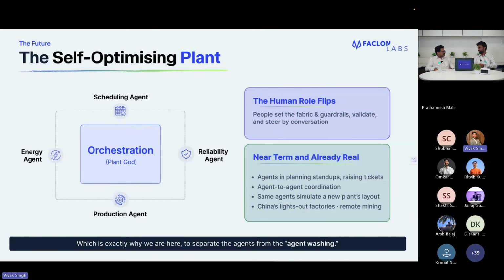Definitely. Maybe at some point in time, the quality agent flags that your main CTQ parameter is now deviating way out of normal. Then there might be a process control agent. The quality agent would flag that your CTQ parameters are out of range. The process control agent then checks what the process parameters were when that batch was produced, and then it would tell me for my next batch that I have to keep these things in mind whenever I am running the new batch of production.